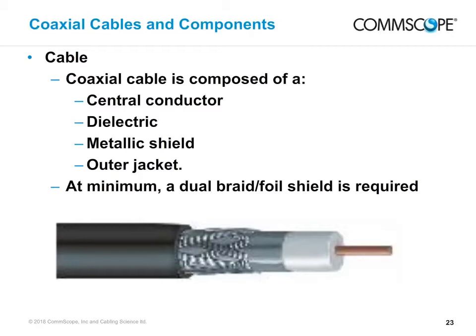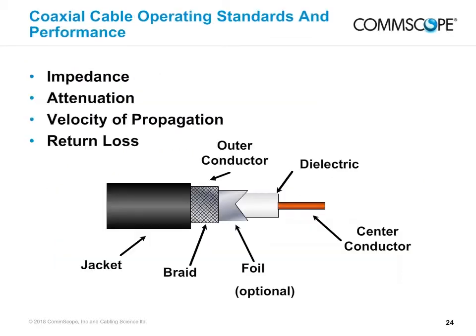While coaxial cable was once the media of choice for data networking because it combines low attenuation and excellent protection from RF interference, it has been superseded by twisted pair and fiber optic cables. However, it is still the medium of choice for video distribution, antenna systems for wireless networks, and for some data center applications.